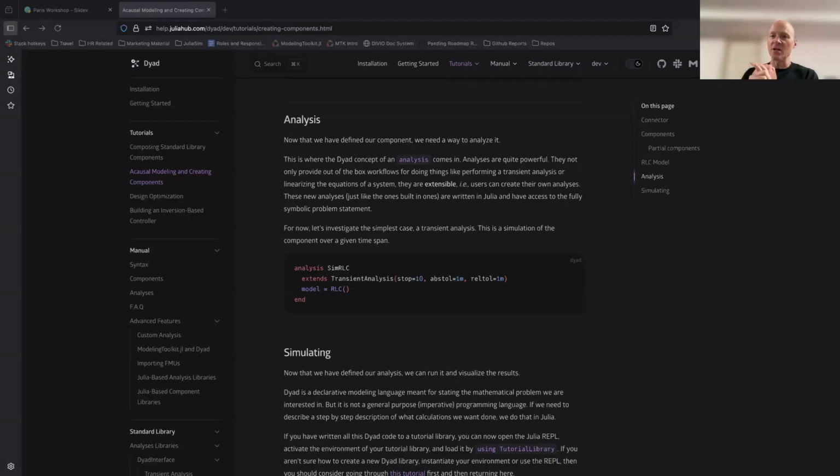Now we do have the same stream connector or stream variable on connectors concept that Modelica has. We have some of the same operators that Modelica has for querying about what's actually in the stream as it's flowing past the connectors. So the key thing is that the path variable thing is independent of direction. If you have a flow path, everything's in that flow path, okay?